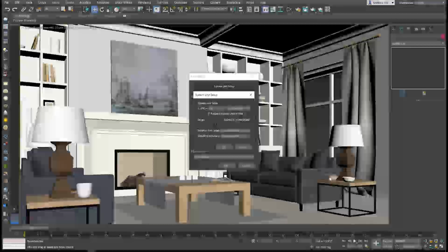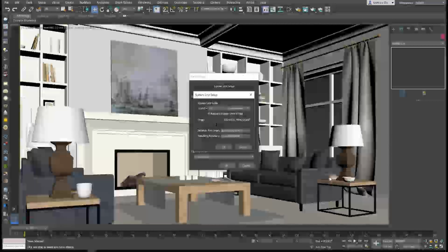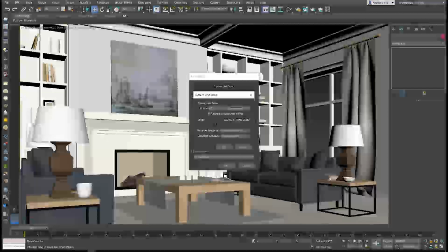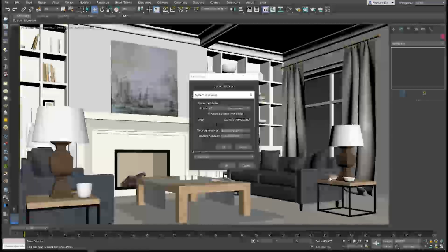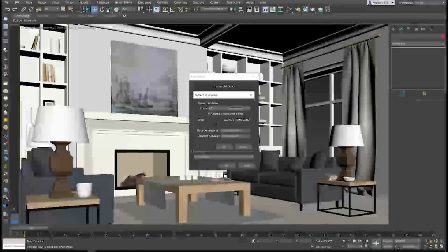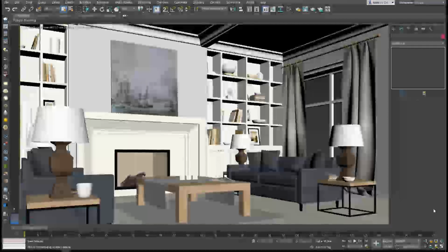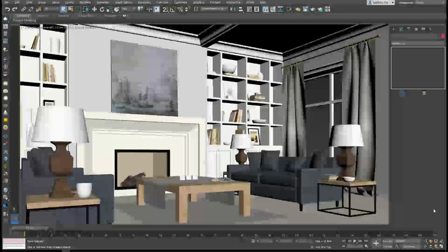So to avoid this as much as possible, be sure that your scenes are roughly centered on the origin of the world at 0, 0, 0, and avoid creating those assets or details on those assets that are smaller, again, than one generic Max unit, basically. Or in this case, we're using centimeters, anything smaller than a centimeter, for scaling your assets on export and import.